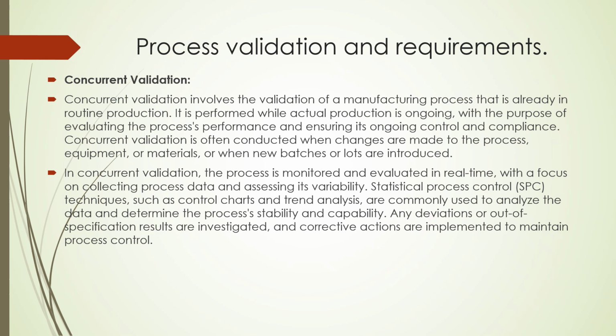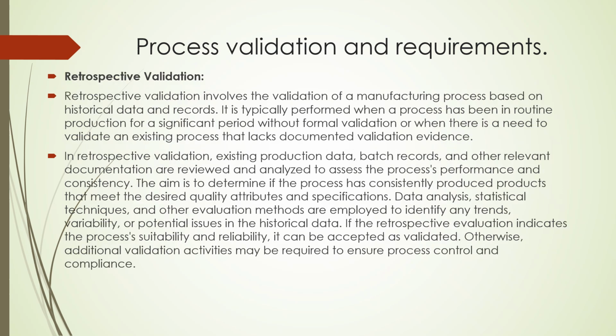Statistical process control techniques such as control charts and trend analysis are commonly used to analyze the data and determine the process stability and capability. Any deviations or out of specification results are investigated and corrective actions are implemented to maintain the process control.